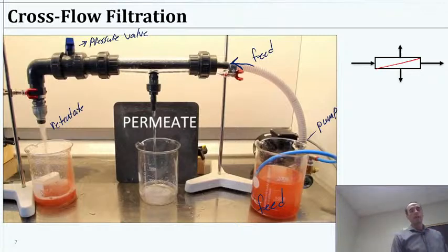So what's happening inside this membrane then, or this casing, is we have sort of two tubes, right? The outer casing, that's the clear plastic that we're looking through. Then the inner membrane itself, which is like a tubular membrane. As the water is passing through here, it's pressurized and it tries to make its way through this membrane material because it's porous, and some of the water escapes. In any direction through this tube, it'll make it into the wider sleeve, and that wider sleeve drains right into this nozzle, right here.